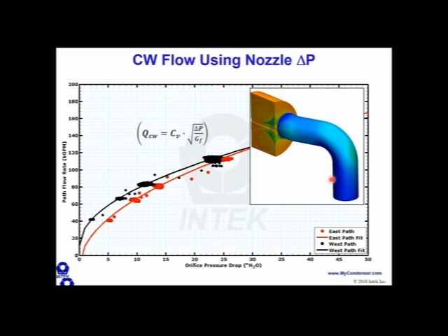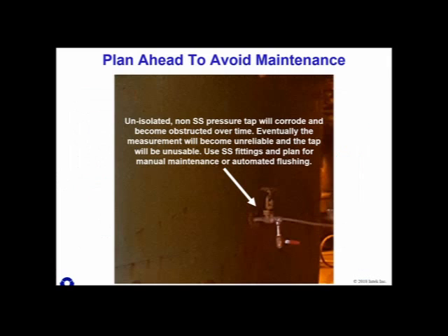Those are all efforts that I would recommend. It's very simple. It doesn't need to be very costly to do that. But then you have some engineering analysis behind your work instructions of where you're going to put your taps and spec your instrumentation. And so this is what the data looks like. There's cooling water flow rate here on the y-axis, differential pressure for this particular water box to pipe. You can get 25 inches at full flow between the water box and pipe for this particular application, which is more than enough to get a measurement of flow rate.